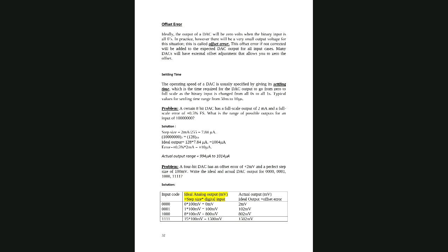Why is having a smaller k better? Because you will get more accurate values. I always give the example of pressure gauges. Say you have two pressure gauges. One pressure gauge has 0, then 5 psi, 10 psi, 15 psi, and so on. But another gauge shows you 0, 1, 2, 3, 4, 5. Which one is better?